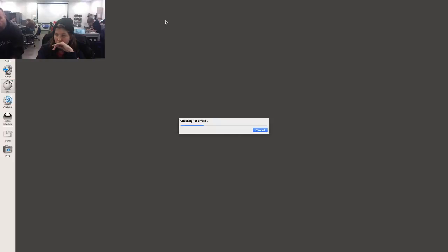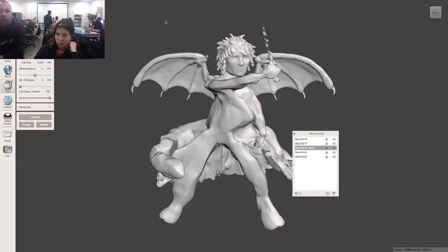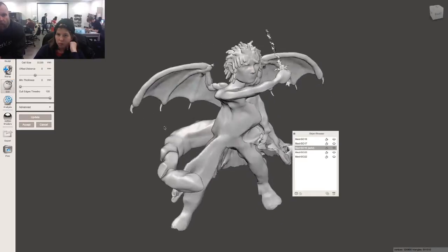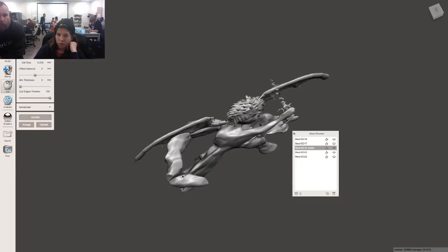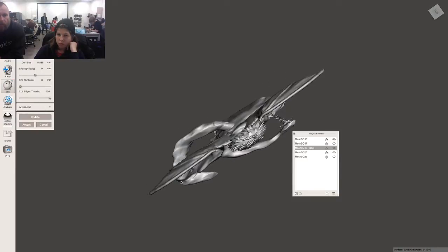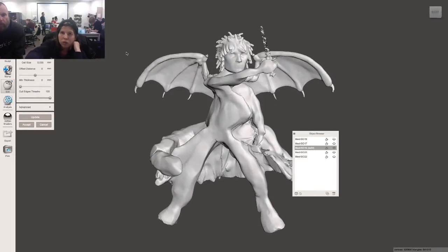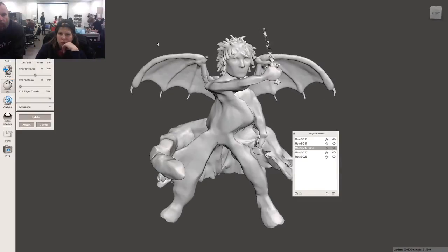So sometimes when you make models in Mesh Mixer, it has so many multiple parts that they don't all jive together. It becomes sort of disjointed components, and then when you put it into Slicer, it won't know what to do because it doesn't see it as a whole. Do you know what I mean? It's just a bunch of separate entities. Like the tail, for example, here, is just the way it was modeled. It sort of has cuts in it. And the sword, yeah, we lost the sword.